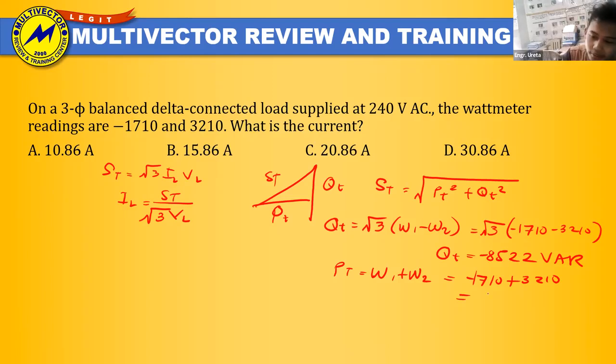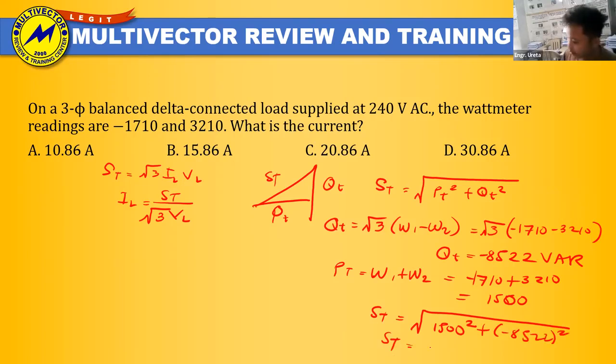That gives 1,500 watts. To get the ST, it is just equal to the square root of 1,500 squared plus negative 8,522 squared. Our total apparent power, ST, is just equal to 8653 volt-ampere.